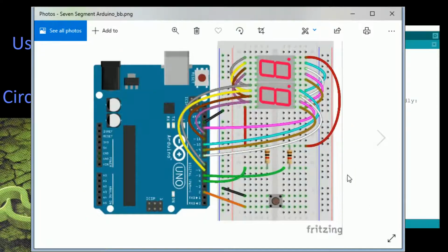So when we get to the Arduino, this is what we have wired up here. This is exactly what I have wired up on our demo today. So here I'm using 2 digits. The nice thing about using these types of digits is that those 7 segments plus the decimal point are the same on each one. So those are A, B, C, D, E, F, G, and decimal point DP. They're just all connected together. In fact, you can see this little gray jumper here jumpers over to this pin, which is the same pin location as it is on this chip, and so on and so forth.